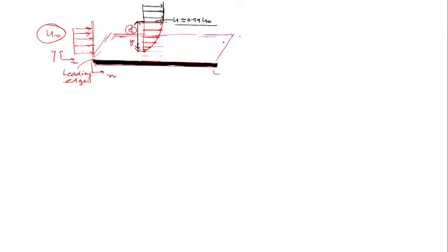Now listen, as we have seen here, du upon dy means change in the velocity. This length will indicate the magnitude of the velocity. A smaller length here means a smaller velocity, and this is y here, so the gradient is there only up to the boundary layer thickness delta. And what you have seen here is the retardation of the fluid motion, because the fluid motion has been retarded. This retardation of the fluid motion is associated with the shear stress.